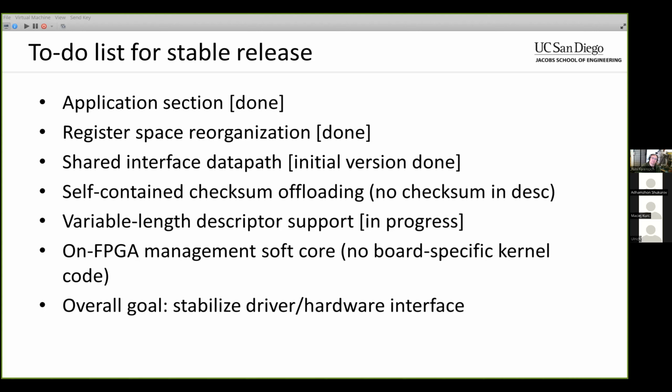Because I think usually this checksum field is 0, so it's not important if you include or exclude it during checksum computation. But if there is something in there, then it kind of derails this. The way the checksum computation works on the transmit direction is that the IP stack computes the partial header checksum and inserts that into the field. So that checksum field will actually have the wrong value because it doesn't include the payload. And then the hardware just computes the checksum of the payload and then updates the field in the header. So it reads out the value, adds it to that and writes it back.